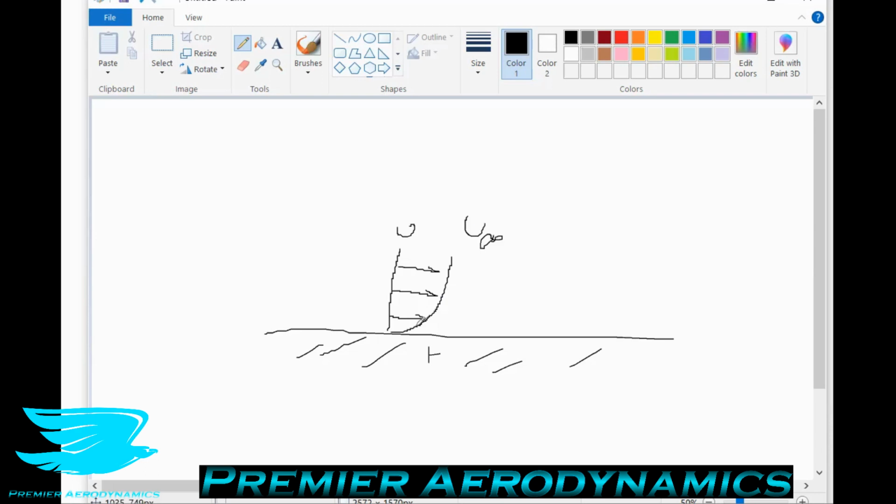Because there is such a high gradient near the wall, it means that we ideally want to resolve this region, because if the values of the velocity, not to mention other things such as the turbulence and dissipation rates and whatever, are all changing dramatically, we want to resolve these things so that we can actually account for them and see how they propagate through the system. If we have a y plus value of 1 or less, we are doing that. If we have a y plus value greater than 1, then we're not doing that.